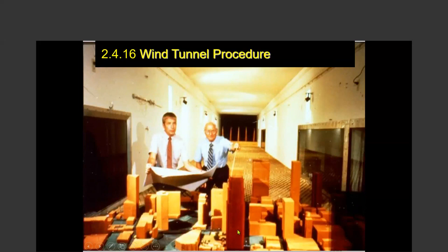So this is the building that is being tested in the wind tunnel. Typically that building will be modeled very carefully in wind tunnel testing. The scaling down of the buildings is the most important thing. So you typically do not test only the building, but essentially the neighborhood, because the neighboring buildings affect wind flow on your building. And you also can play what-if scenarios. What if this neighboring building were to disappear 5 years from now? What if another building would come somewhere in that vicinity 5 years from now?